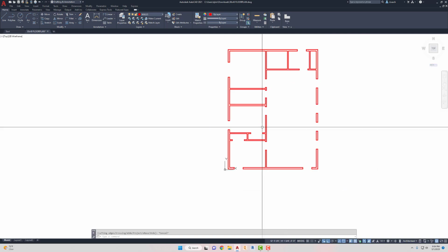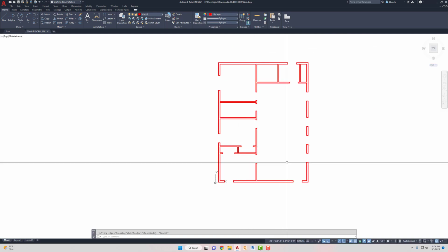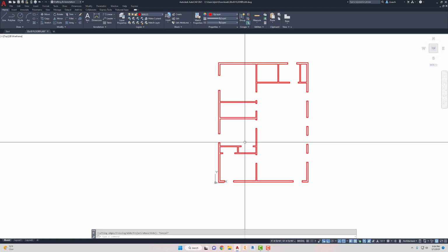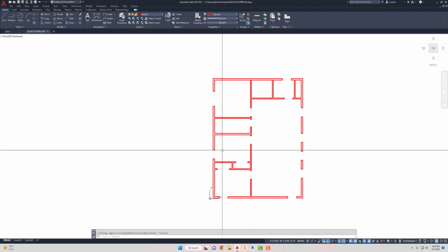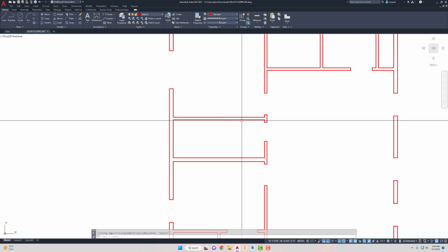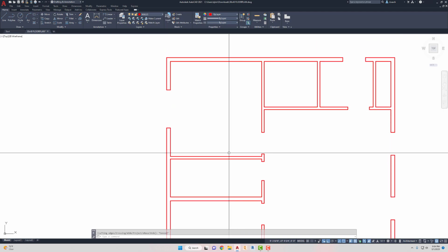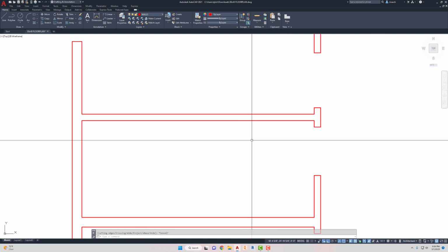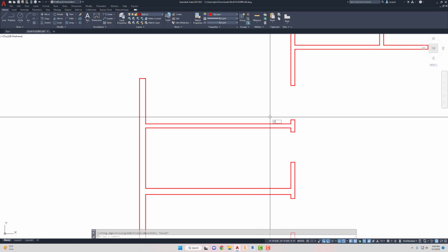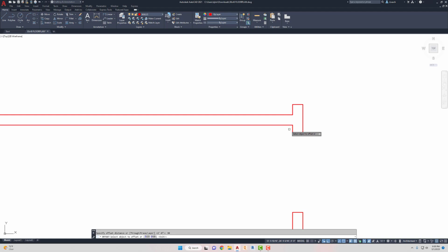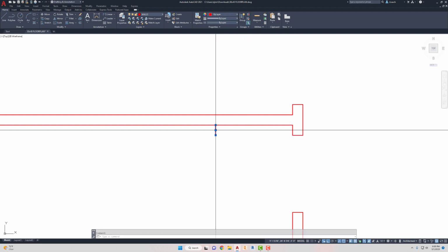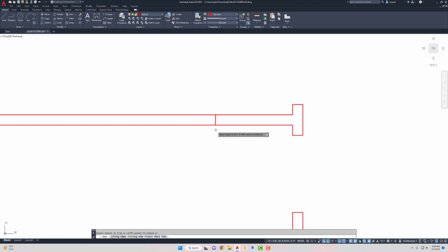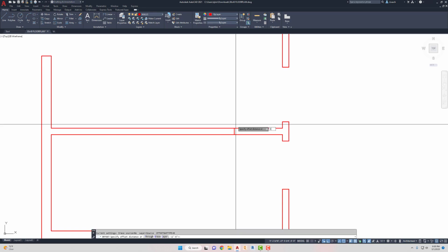All right, so I think we got our opening. So we got the 2 windows at the bottom. There's 3 windows and a door. There's a door, closet door, bedroom door, window. Oh, there's a little slider door right here for this to get into the bathroom from the master bedroom. So if that's 30 inches, I'm gonna have at least offset this 30. Probably want more than 30. Let's say slider. It's really a pocket door. I think it's a pocket door. I'll set this 30.